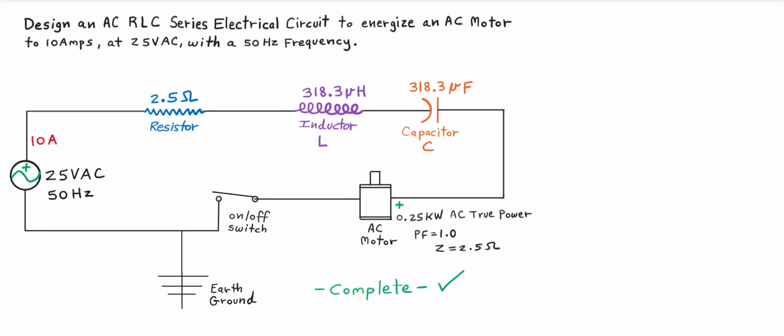So try the one-to-one method, and then from there after you can then adjust it for what you need, because the circuit is in resonance. So when you calculate the correct impedance, it is also equal to the resistance.